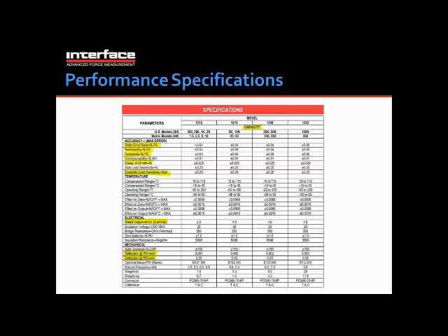Further below, around the middle of the page, you see the rated output values for the different capacities. And further down, you see the amount of deflection across the load cell because of the load at capacity that is being placed on top of the load cell.